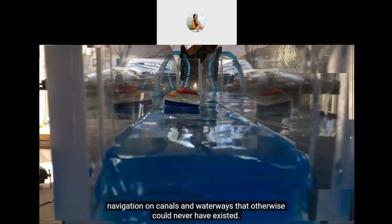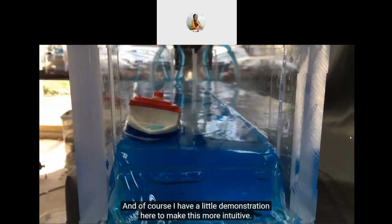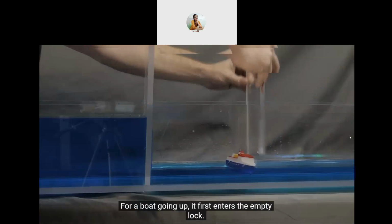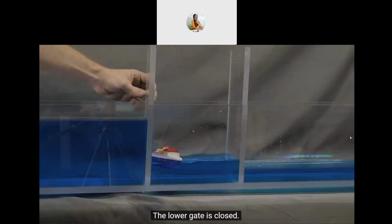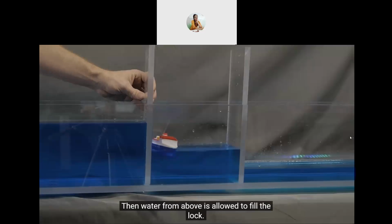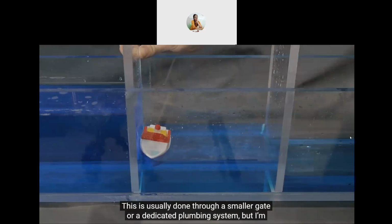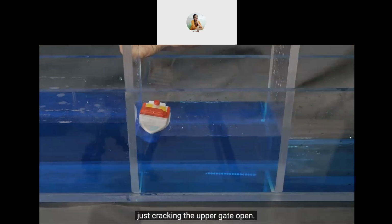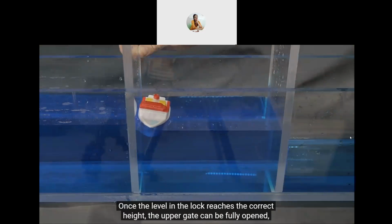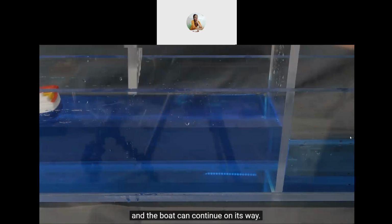The way a lock works is dead simple, and of course I have a little demonstration here to make this more intuitive. For a boat going up, it first enters the empty lock. The lower gate is closed, then water from above is allowed to fill the lock. This is usually done through a smaller gate or a dedicated plumbing system, but I'm just cracking the upper gate open. Once the level in the lock reaches the correct height, the upper gate can be fully opened and the boat can continue on its way.